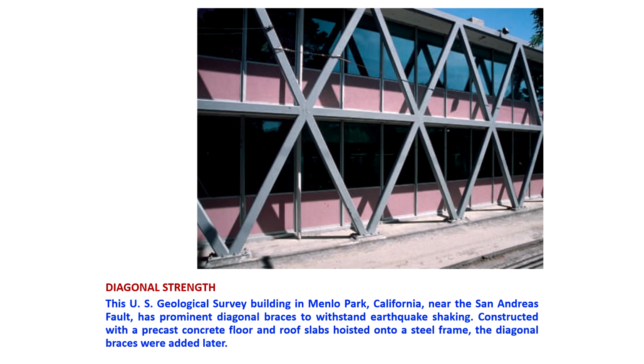People have experienced having weak floors, and then, without bothering about the aesthetic architectural sense, they have put in diagonal brace bars. Diagonal braces have been put in many buildings, not only in the US but also in Japan, to safeguard these buildings. So in future at least they are safe, and whatever ground shaking comes is taken up by these diagonal braces.